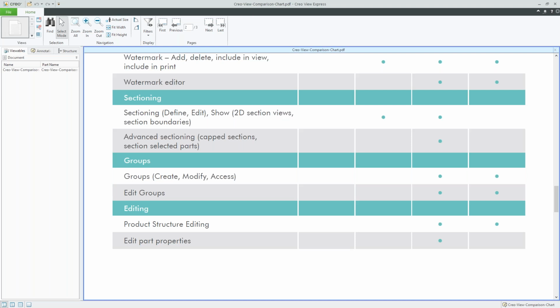If I'm thinking of this correctly, you're using not just Creo, but that sounds like a SolidWorks file. You would have to set up a SolidWorks publisher that will allow those to be visible. If I'm visualizing what you're seeing when you say yellow cubes, that looks like what I would see when looking at SolidWorks files. So those will more than likely be SolidWorks files that just aren't published inside of Creo View.